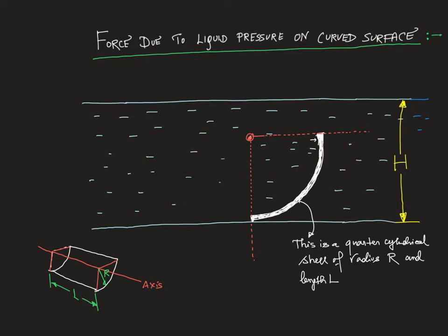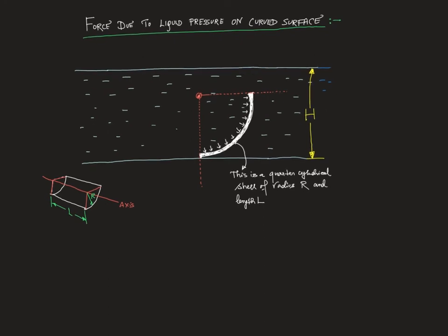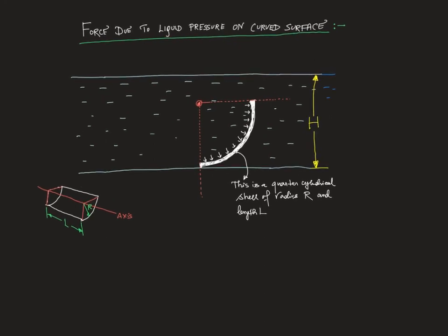So liquid pressure applies here, right? Liquid pressure is applicable here. So usually what people will like to do is consider a small area dA and calculate the height and the force, calculate the force and integrate. We told you before that we will not do any such thing. Rather what we will do, we will choose an appropriate free body diagram to calculate the force. Now here the free body diagram that we will choose is the following.